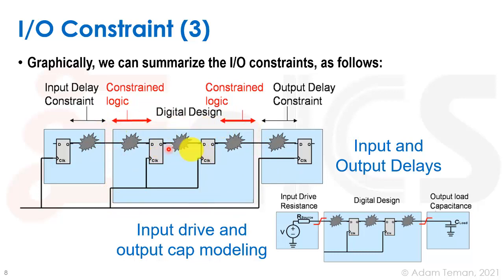And when we look at reg to reg paths, from one register to another register, where the clock source is at some common point inside the design, we know everything we need to know about this type of path. We have the registers with their delay and their setup and hold. We have the propagation delay of the combinatorial block in between, and we have the entire clock path that gives us the skew or the propagation of the clock. So we have no problem with these reg to reg paths, and luckily, the vast majority of all the paths in our design are going to be reg to reg paths, and we'll treat them like that. Most of our optimization is going to be done on reg to reg paths.